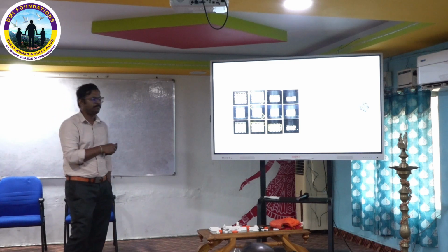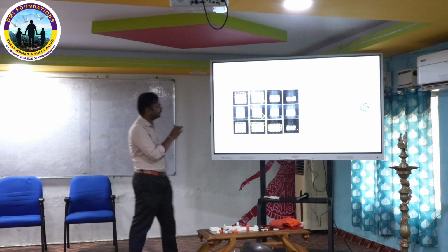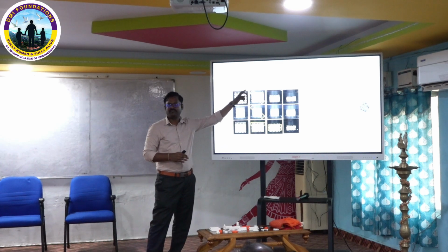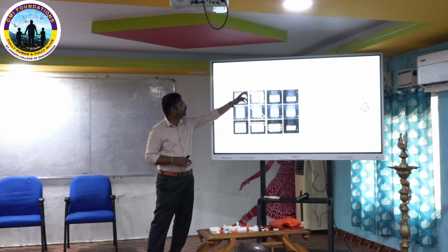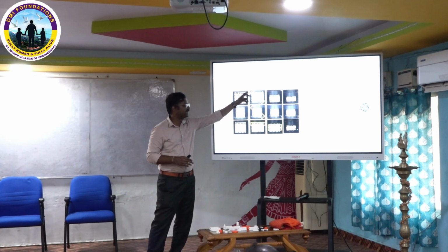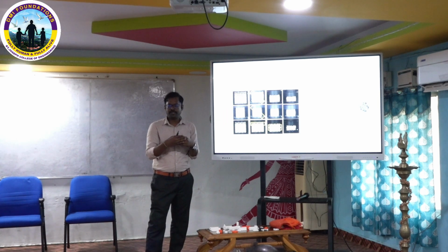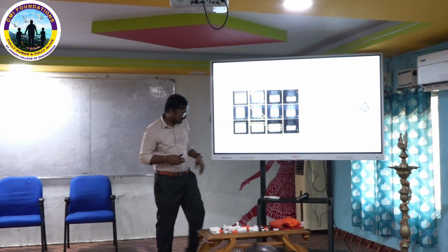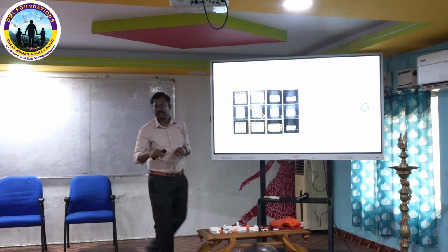Then this is the Kelvin based lattice. It is a bending dominated structure. For 10 and 20% I have shear band failure. That means the applied load is transferred along this incline and deformed as a bending dominated behavior. So I get more plateau region, a smooth plateau region.